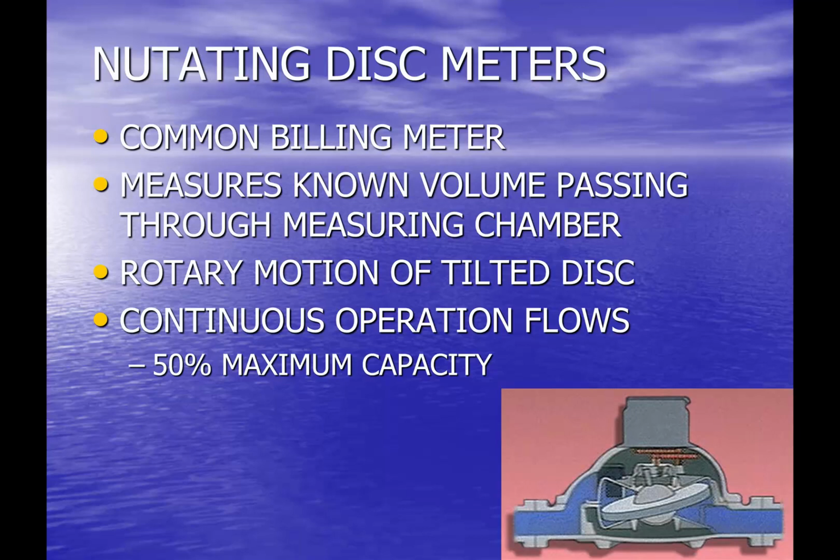see that it's got to push that disc around. So yeah, there's some obstructions in the flow path. But again, you take that into account as the meter is designed and sized. The higher the flow and the smaller the meter, you're obviously going to have more head losses.